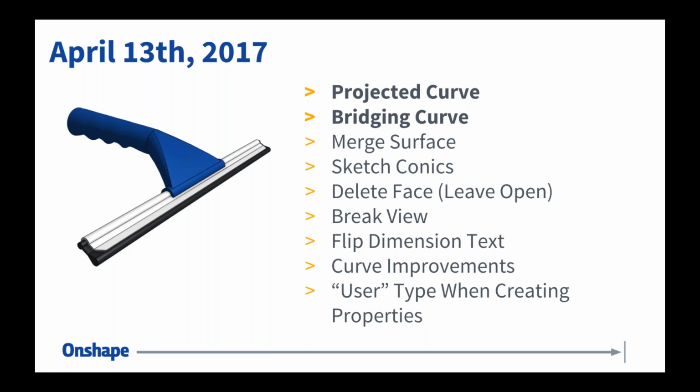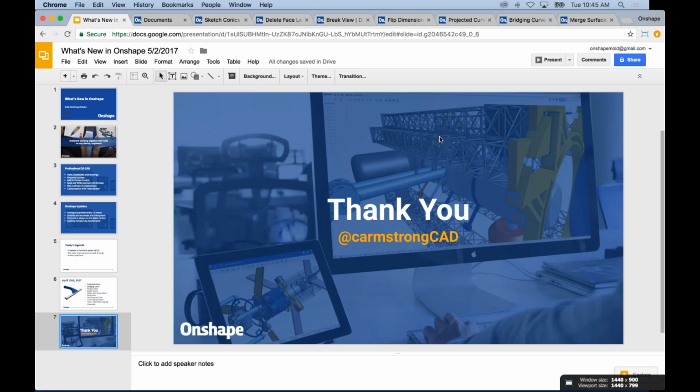Model-based definition means that you're defining all the important factors in the actual model. So, not just adding dimensions at the sketch level, but also defining the tolerances between faces, the tolerances of dimensions, or I might have concentricity callouts, or all of those things actually built into the 3D model rather than reflected by the drawing. So model-based definition is a growing trend where you're foregoing the typical drawings in favor of adding all of that information into the actual model. Right? All right, so let's move on.